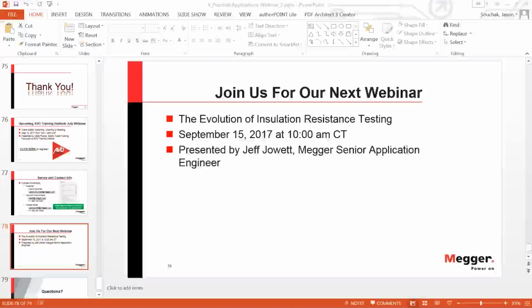Well, if the cable is already faulted, you cannot do any type of test that we talked about because you cannot charge the cable anymore. So on a failed cable, you cannot do any type of withstand test or diagnostic testing. Can I just add? After you repair the cable and put a splice in, you just pick up where you left off with the VLF testing. So if it failed 20 minutes into your test, you repair the cable and then pick up and do 40 more minutes. But you have to repair the problem first.